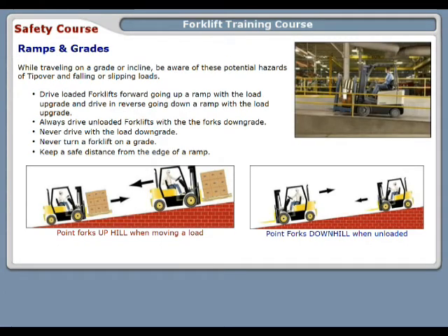While traveling on a grade or an incline, be aware of these potential hazards of tip over and falling or slipping loads. Drive loaded forklifts forward going up a ramp with a load upgrade, and drive in reverse going down a ramp, again with a load upgrade. Always drive unloaded forklifts with the forks going downgrade. Never drive with a load downgrade. Never turn a forklift on a grade, and keep a safe distance from the edge of the ramp.